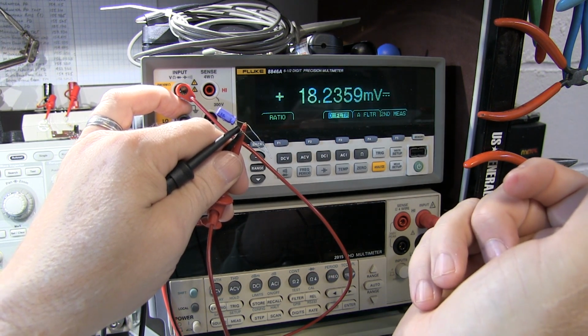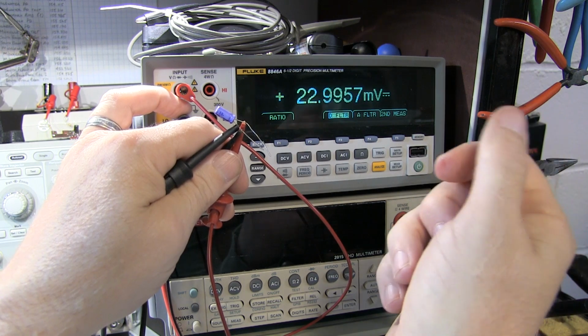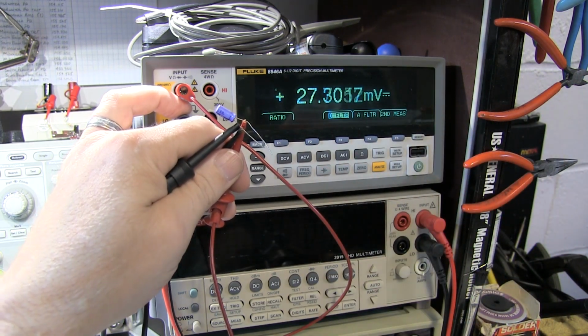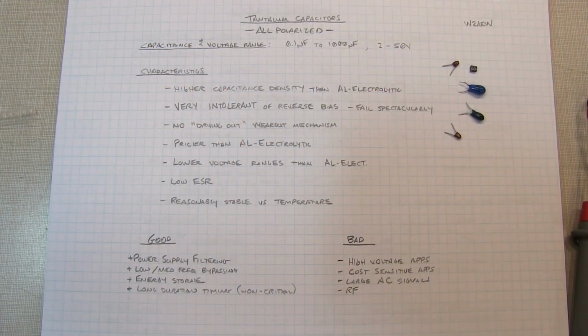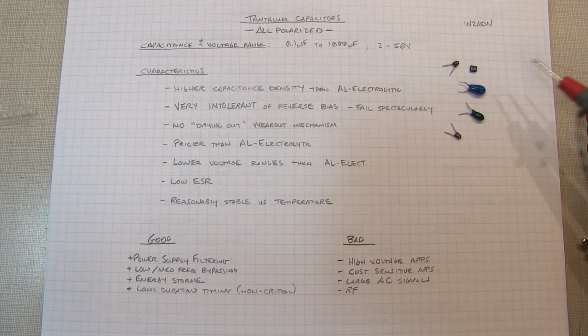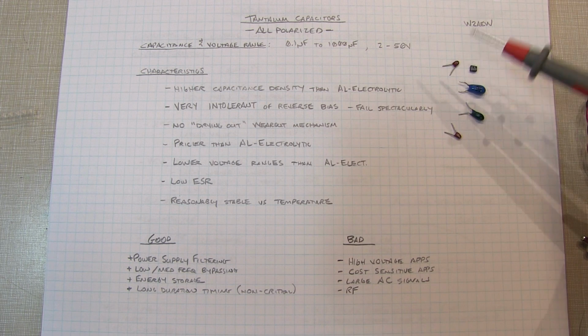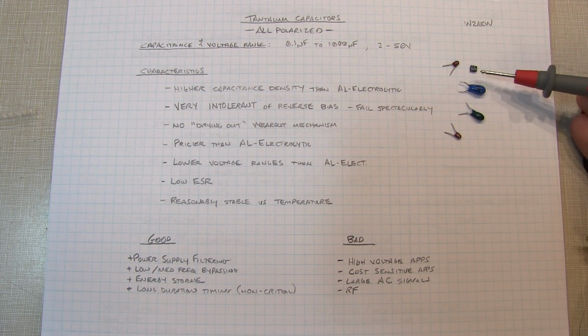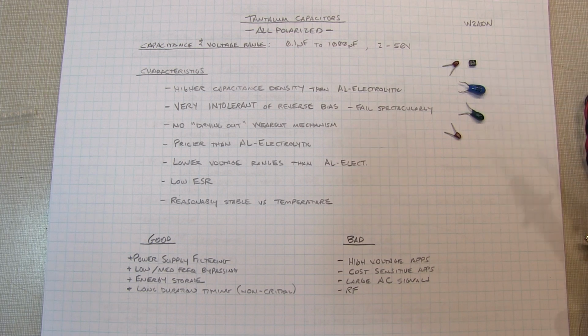And this is, again, dielectric soakage, and it can really wreak havoc with precision timing circuits. So before we leave the topic of polarized capacitors, let's talk about the other type that you'll see, and that's typically these tantalum capacitors. I've got a couple of examples here, some radial-leaded and then a little surface mount device here. Tantalum caps are all polarized, and I would say they're wildly polarized, and I'll tell you what I mean by that in a moment.